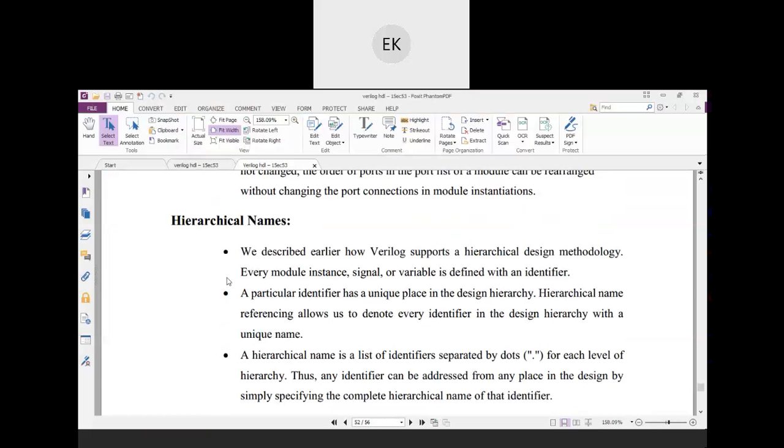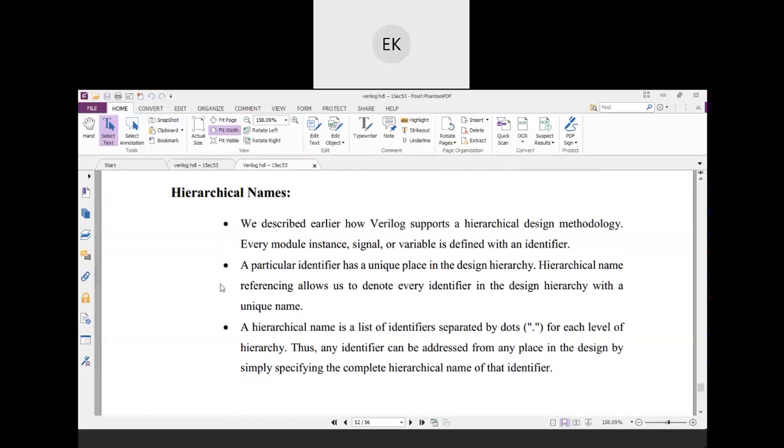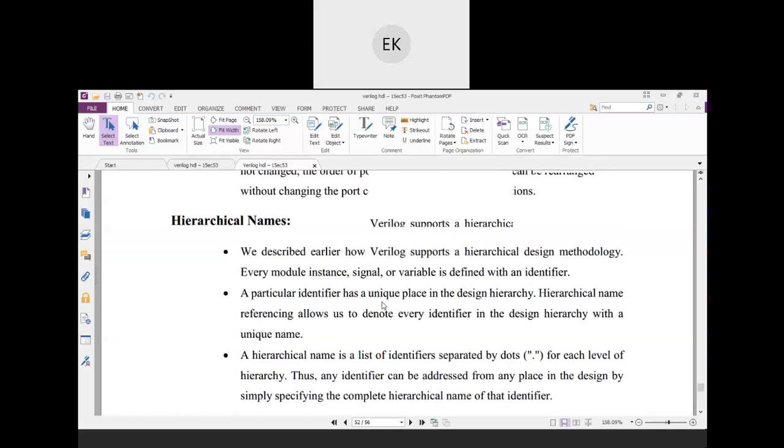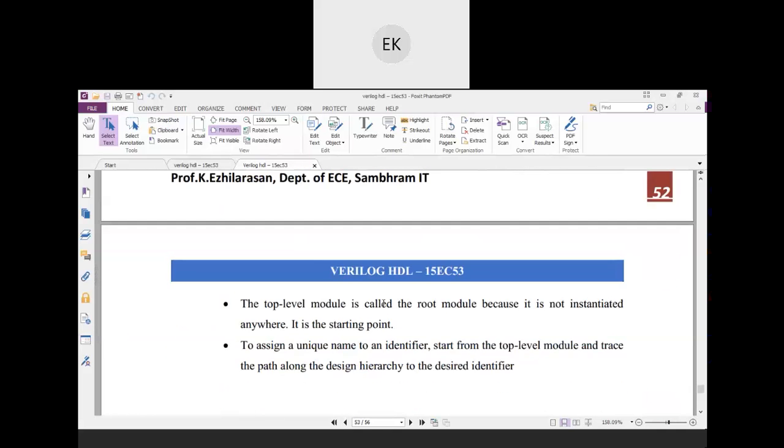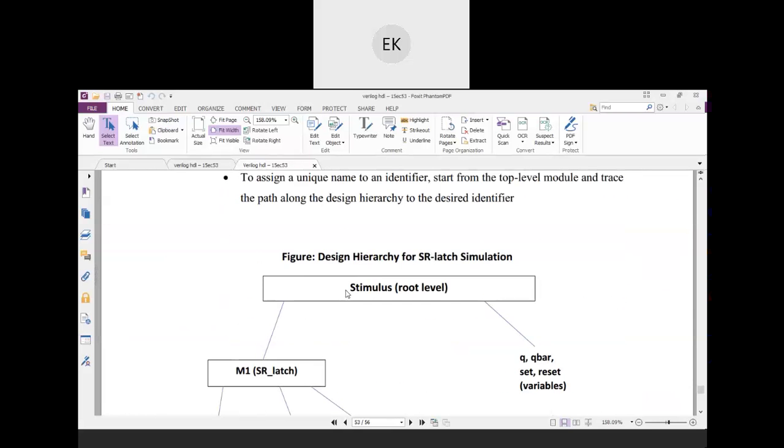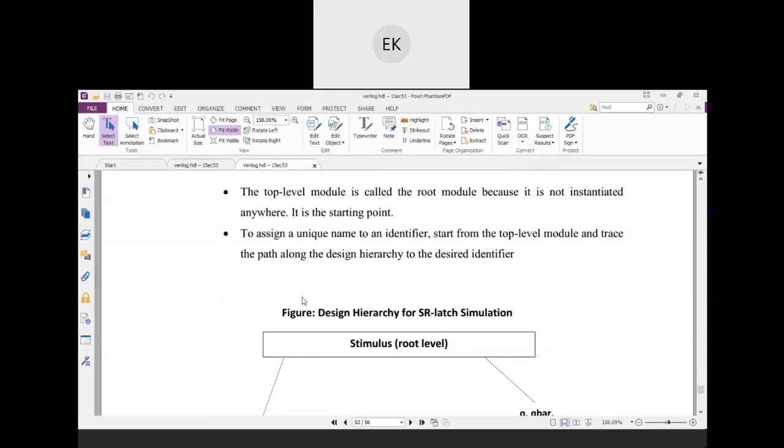But what I did is the mapping with name-wise instantiation. See, the name-wise instantiation we did. But here we did position-wise instantiation. See, but here I did both actually. It is position-wise as well as name-wise. Name-wise I did, but it followed the position actually. So this is the alternate way you can write.